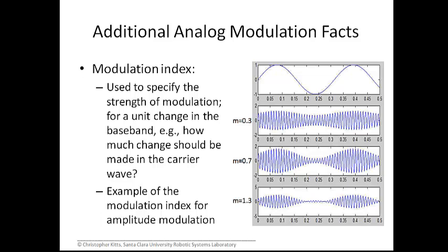And so this notion of the modulation index is something that sometimes comes up in satellite operations because it contributes to the ease or difficulty with which you have in locking onto a signal. I can tune into the carrier wave at a certain frequency, but being able to really discriminate between changes in amplitude or frequency or phase is critical because that's how I'm doing the demodulation process. That's how I'm extracting the information. So modulation index is an important factor for this reason.